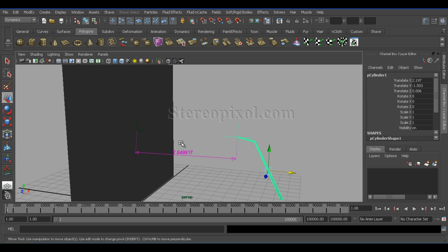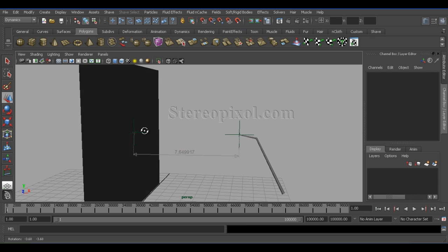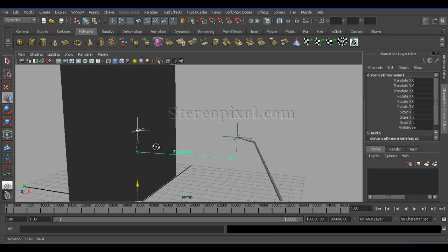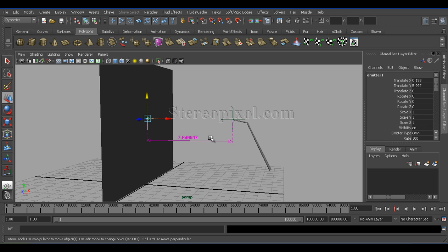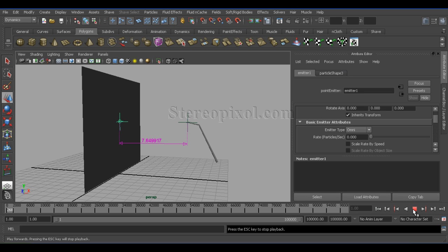So that will be the logic, and to create that, select that particular emitter. Oops, it's not the surface. Okay, yeah. So just select the emitter. This is the parameter in the emitter. It's called rate. So if we hit 0, you see there will be no emission happening. And by default, whenever I hit it to 100, I will see my emission is happening.